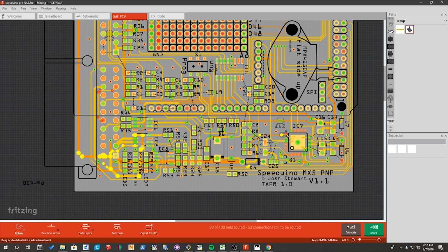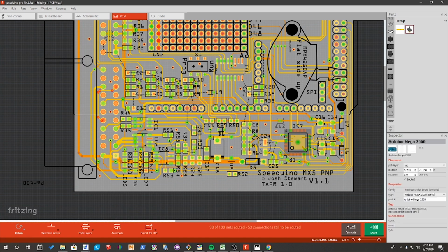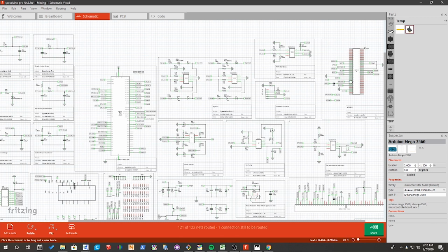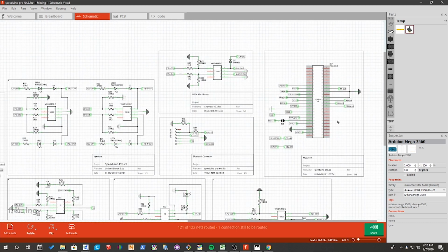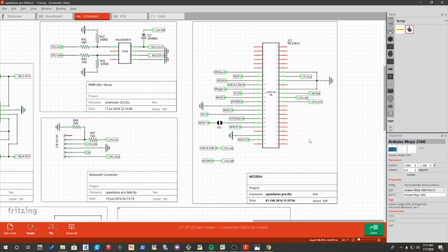So once we figure that out, we've got to figure out, okay, what is this IC7? What is this integrated circuit? And in order to do that, we can actually go all the way over to the schematic in Fritzing and then zoom in to IC7, which is going to be right over here. And when you zoom into IC7, we can go ahead and look at pin 37, which is what we were just seeing, the 12 volt switched power, and we'll see that IC7 at pin 37 is key switch, so that's going to be the switched 12 volt power that comes into IC7.